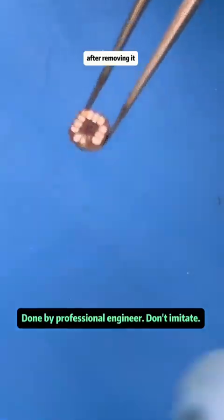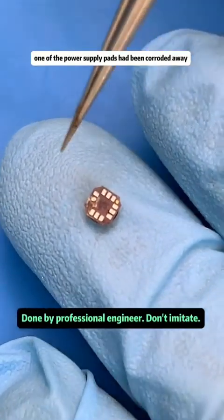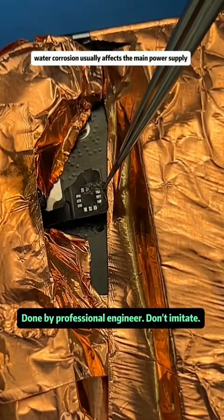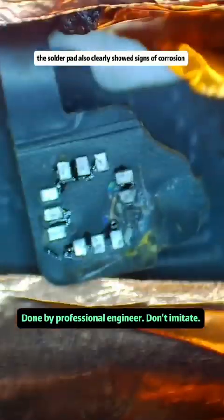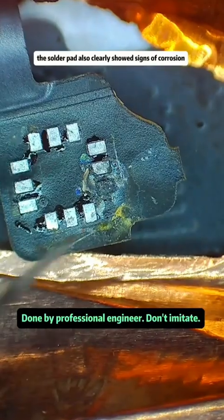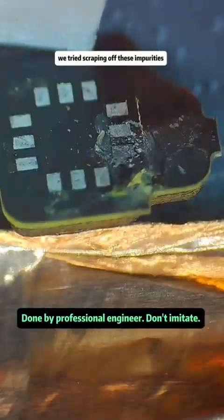After removing it, we could see that on the solder pads, one of the power supply pads had been corroded away. Generally, water corrosion usually affects the main power supply or the high voltage rail. The solder pad also clearly showed signs of corrosion, and one of the power supply pads was no longer visible. We tried scraping off these impurities.